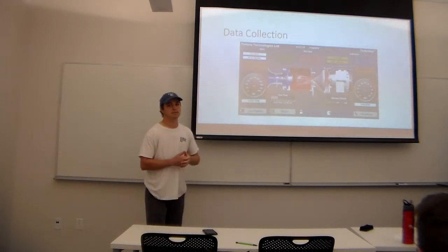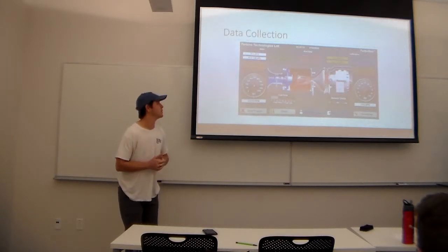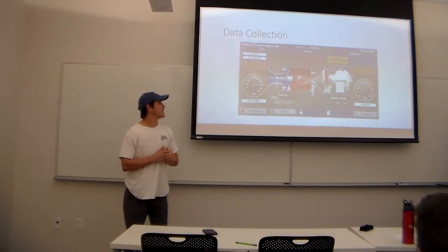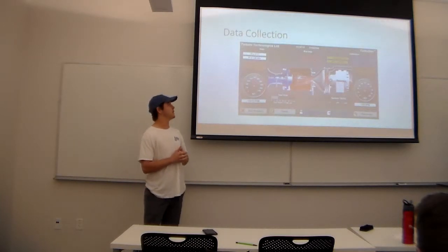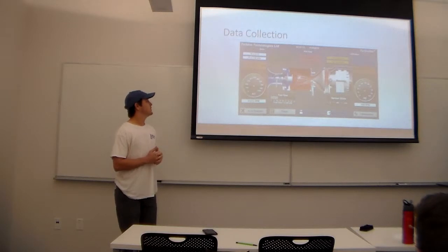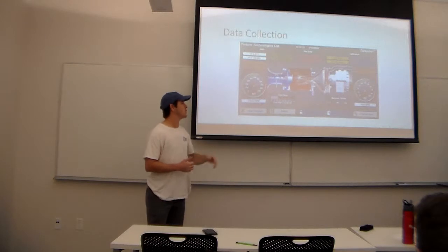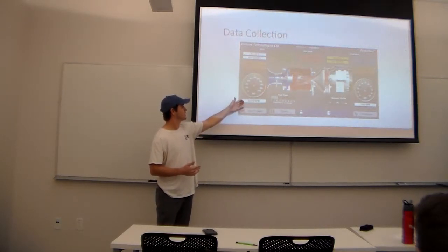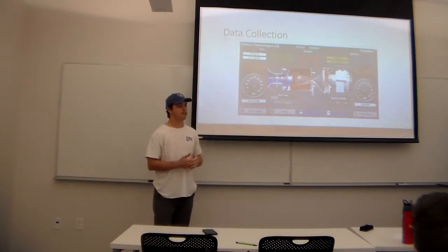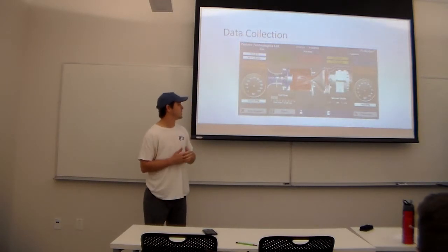So here's the TurboGen software that we use to calculate parameters that we need to know. There are 5 Type K thermocouples that are placed throughout the system on each individual component. You have the inlet, compressor, power turbine, and then you have your free turbine, and then your exhaust. As you can see right here, you have voltage, current, and RPM on the first power turbine. On the other side, you have your power output of the generator and your free turbine RPM.